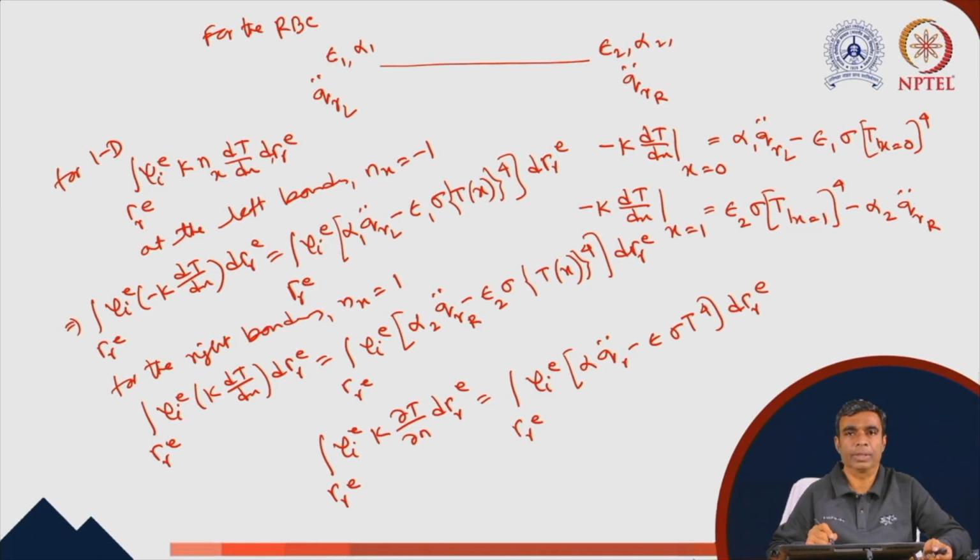So when we substitute these expressions into the weak form, we have to substitute the trial solution expression for the temperature for both the convective and the radiative boundary condition contributions, and by that we got our expressions for the left hand side matrix contributions and the remaining terms contributed to the right hand side load vector.